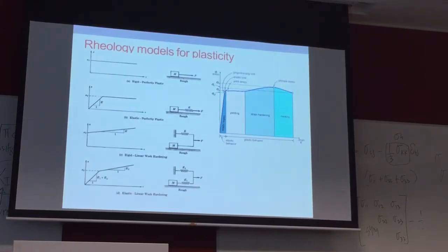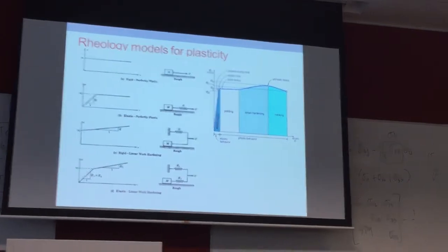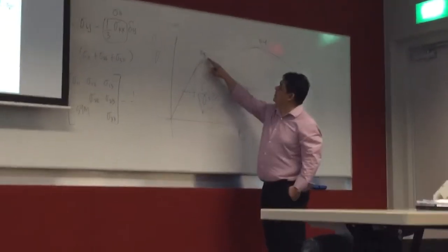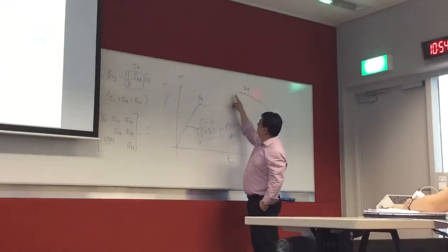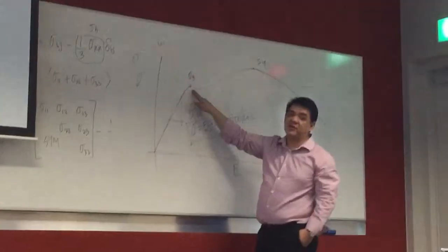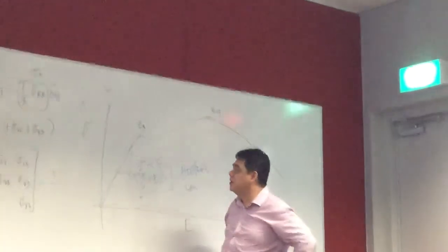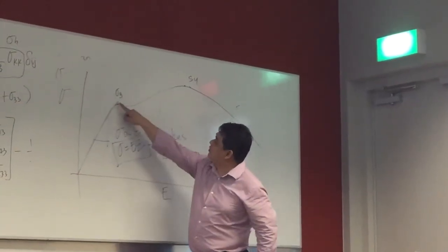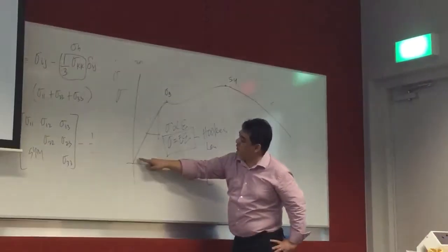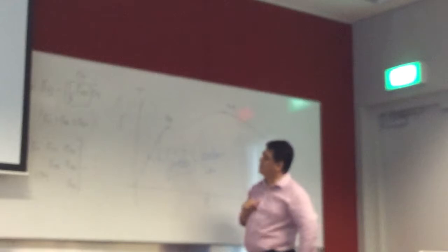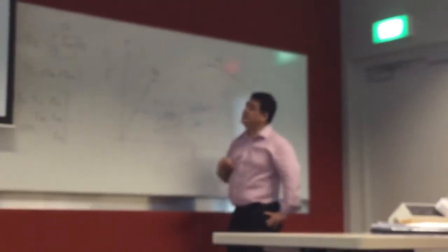Have a look at this one here. Ideally, or in testing, this is what you can observe. Of course, some materials can go straight there, without this part. Here it's quite easy to identify your yield if the material behaves in this manner when you perform tensile testing. The thing is that if you have this one moving there, then you have to estimate that yield somewhere. Probably you have that in your lab, wherein you have a 2% yield. Just draw a line 2% from that, and then pinpoint that yield.